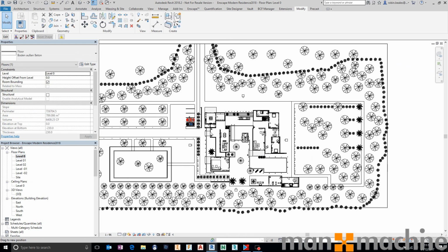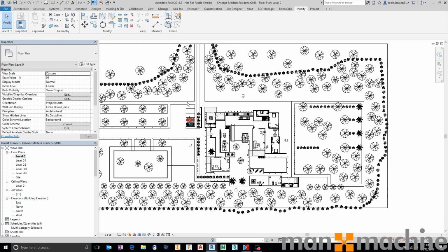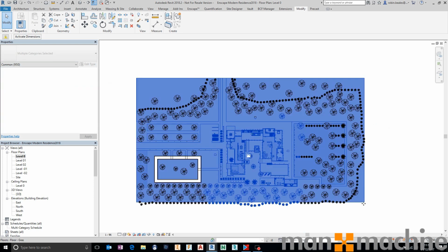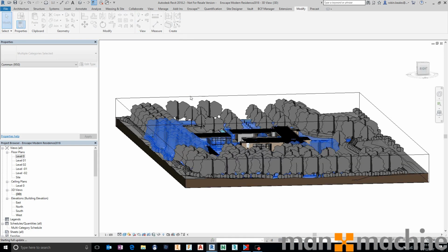Let's put a window around my building and the area that I would like to put a section box around. So I'm just going to use a slightly different piece of functionality just because my Revit's having a little bit of an argument with me, so to speak. So let's just put a selection box around something inside of Revit. Turn on my section box, slightly different way. This will again update Enscape very quick.